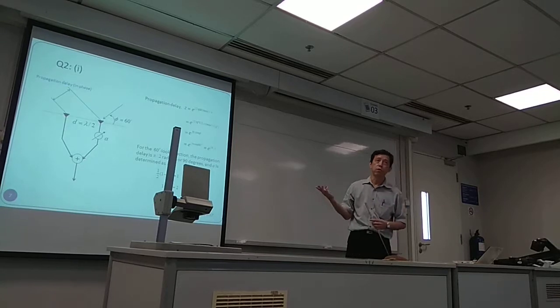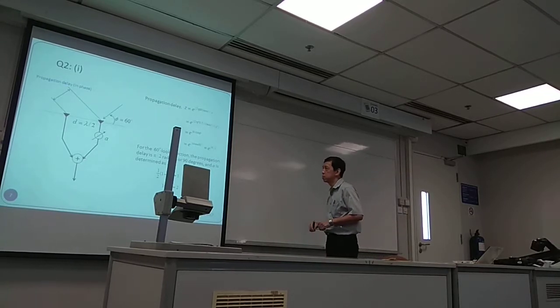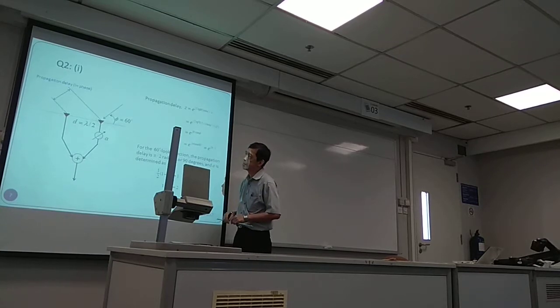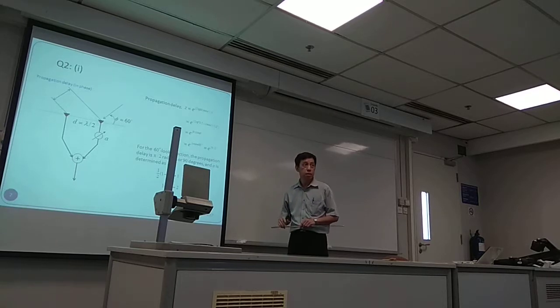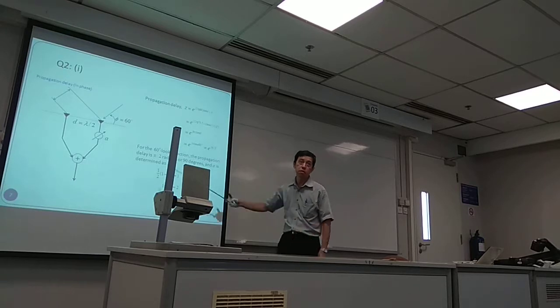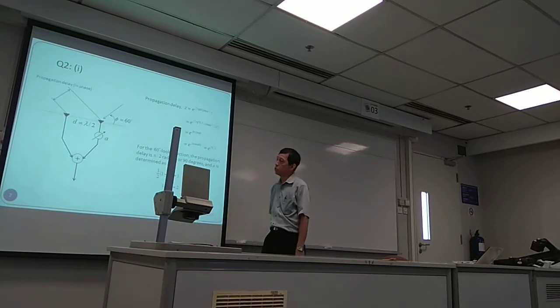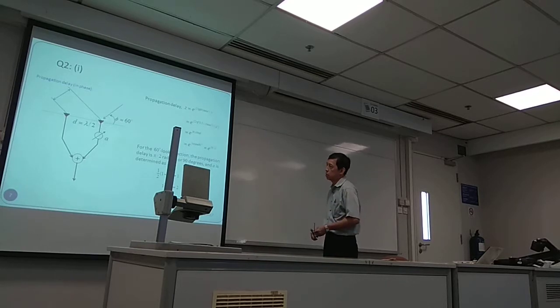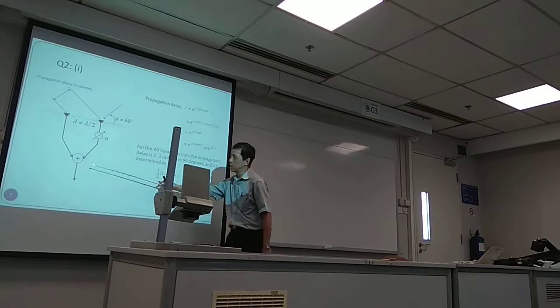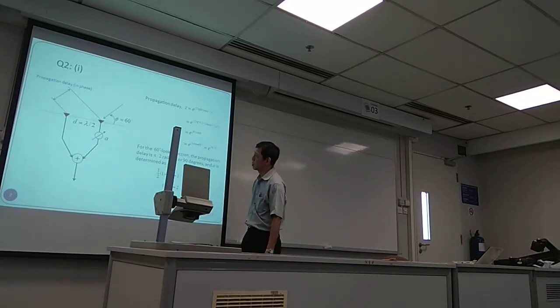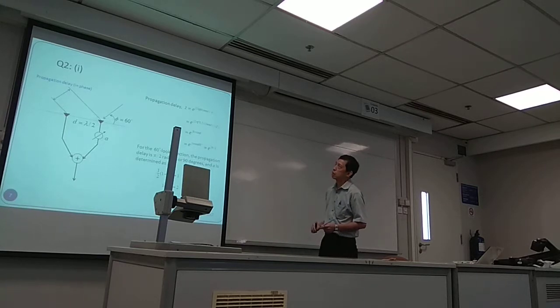Right? So that is basically what you do when you study interference pattern. If you still remember, if you have done physics before, the double slit experiment, so it's exactly the same concept. Okay, so signals, when they are in phase, they add, and if they are out of phase completely, 180 degree out of phase, then they subtract, or in fact they cancel each other. Okay, so then with the output of the summer, of course, you have the output signal due to your target.